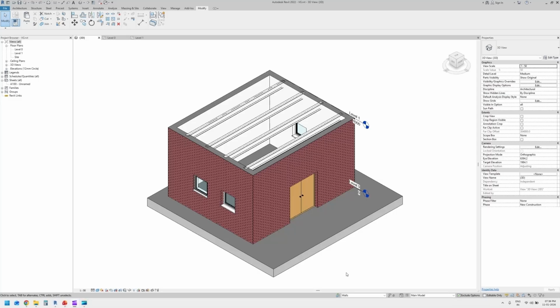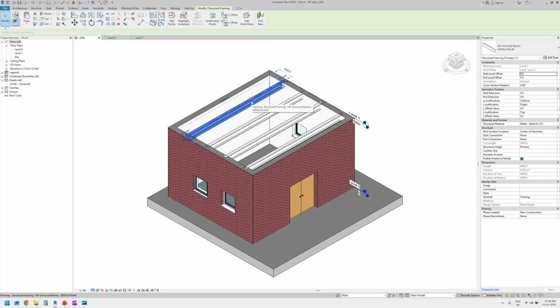Sometimes you have checked with all the possibilities within the model, but you are still struggling to find out your element visibility. Sometimes the problem is not the view, but the family itself. Let us go into one of the beam families to find out from where a family element can be hidden.